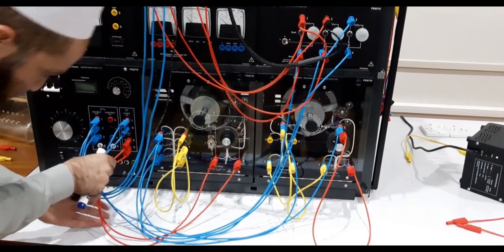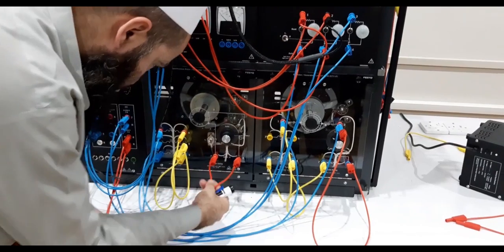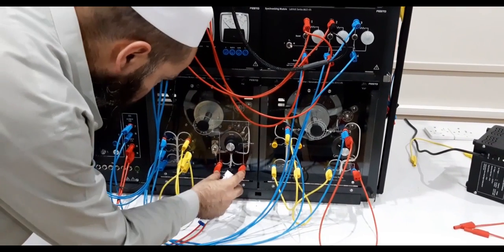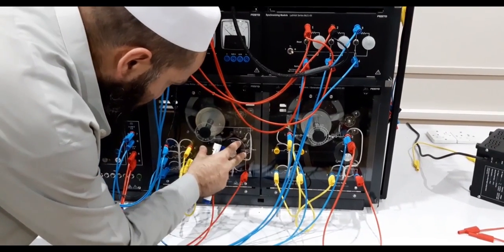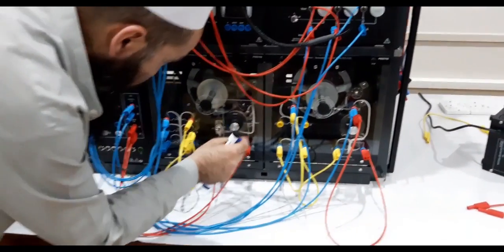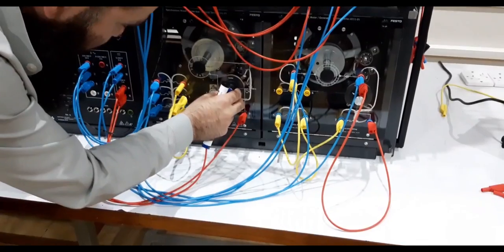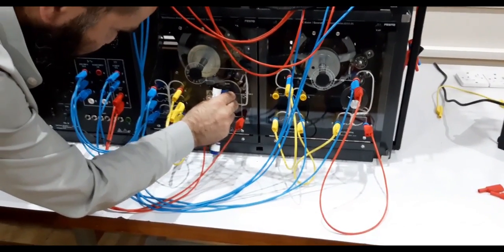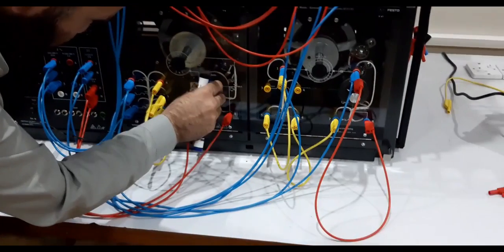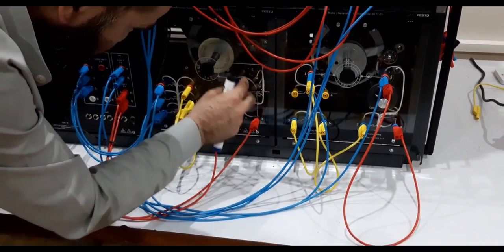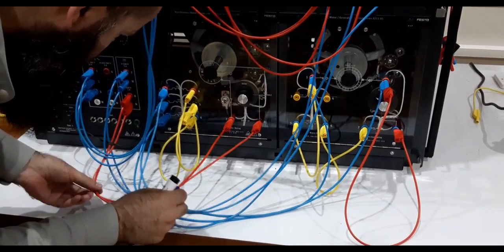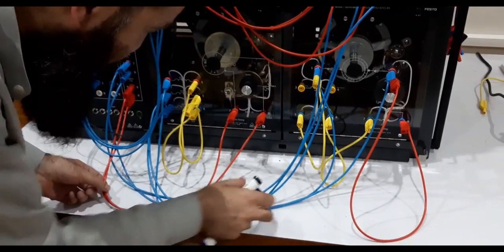So we are connecting here by means of these two connectors. We connect the fixed DC supply to the rotor of the synchronous machine, and we will vary the field current by means of this exciter. So moving the knob will change the field current. So by means of the exciter we will change the field current, and it is connected to a fixed DC supply.